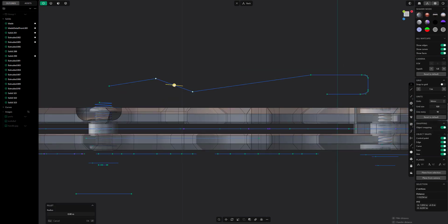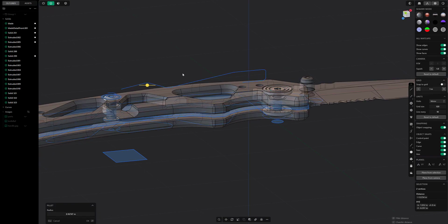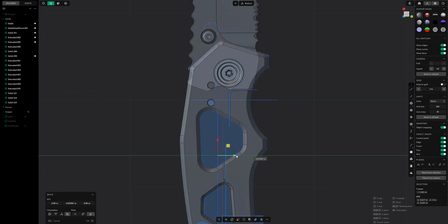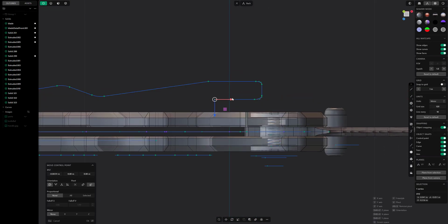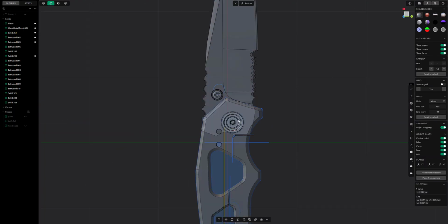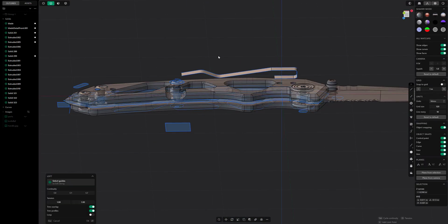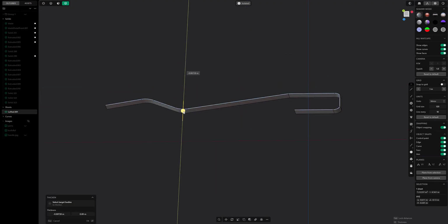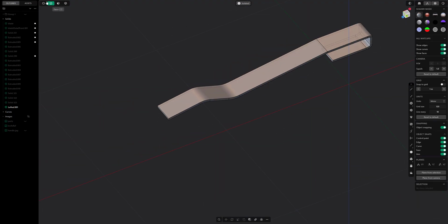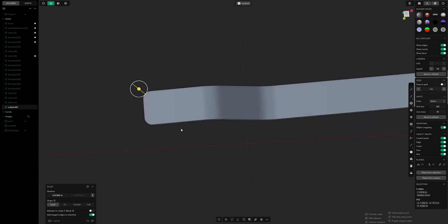On these, I'll go ahead and fill these, and you can see those soften up real quick. And then I'm going to take the edge or the curve, and I am going to just make sure everything looks quite nice, and then we can duplicate it and then loft to get the actual sheet. Once we have the sheet, we can grab it and use thicken to bring thickness to that shape, and then we can make the corners a little bit nicer.